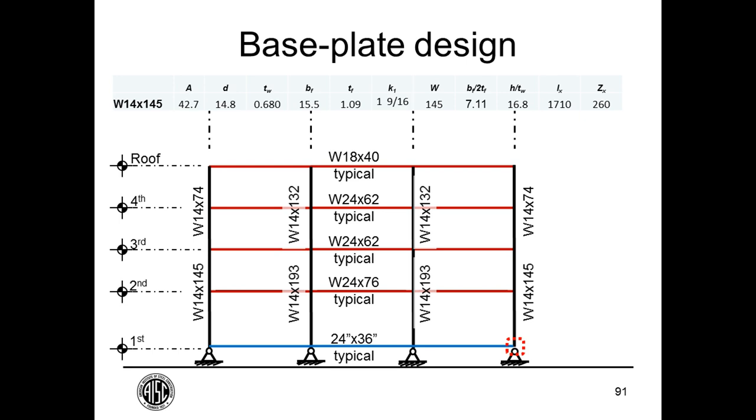That grade beam is a stiff flexural element, and the column goes into reverse curvature. So the stiffness of that grade beam is intended to model the finite rigidity of the foundation system. So it's not modeled as infinitely rigid, but it's not modeled as infinitely flexible either.